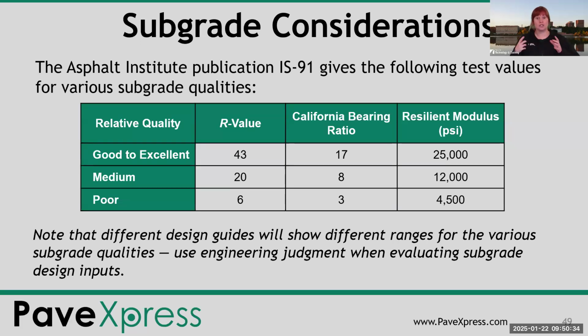Those correlations between some of the different tests, like CBR, you can get an R value, they all kind of will get you an answer, but all of those equations are empirical. They're our best guess. Estimates. Yes, they are estimates. They are intelligent guesses, but they are our best guess on those. So the more that you need that pavement to really be bulletproof, the more I would encourage you to actually do the resilient modulus testing, as opposed to trying to work out something that is close. I would go with the actual test. That is my PSA for the moment.